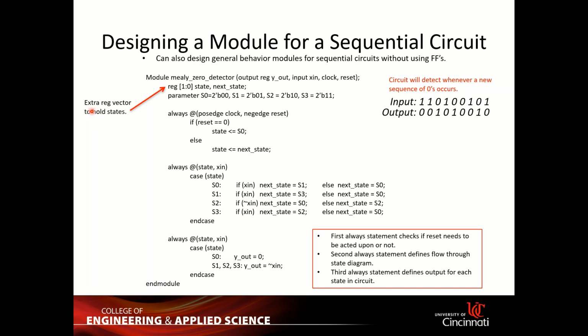What is missing here is you need some internal state of the machine. So you need to define the internal state. You can use the reg type to define 2 variables. One is for current state, one is for next state.